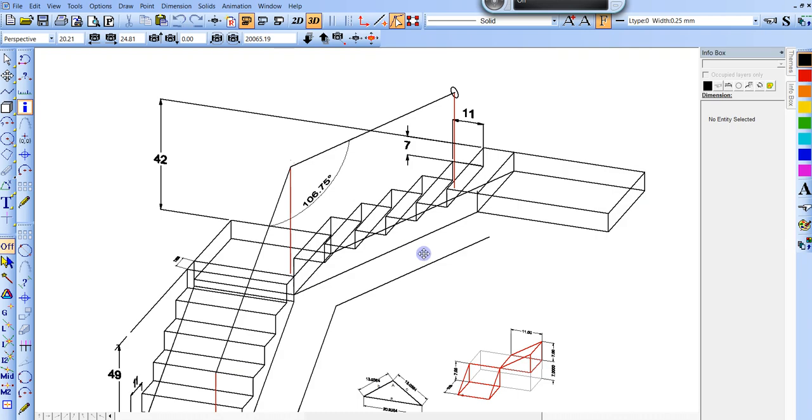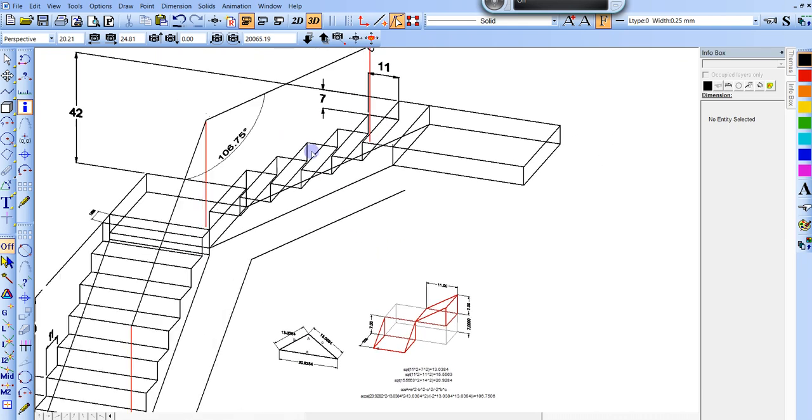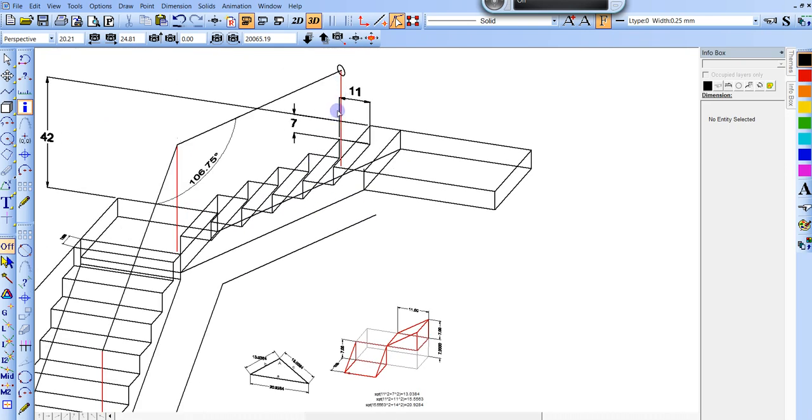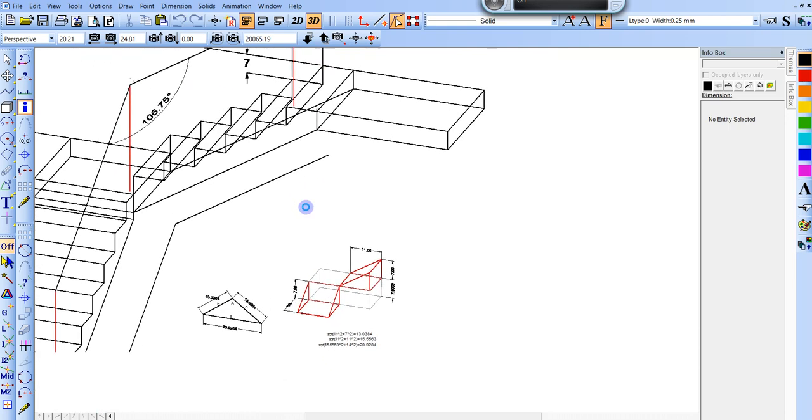So 106.75. Then when you put that on the table, make sure you center punch at the top, on both pieces. I would do it at the end and very close to the handrail, almost in the weld zone, a center mark, so that when you cut it and flip it around, you know where the top is. Otherwise, it's easy to think you're putting it together right and there could be an error.